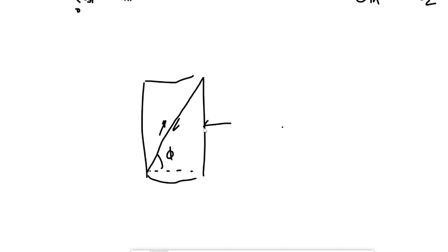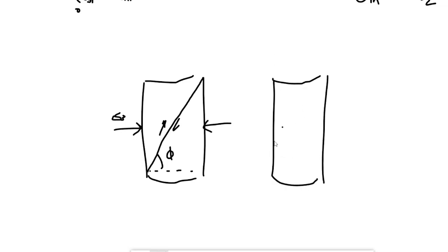And you start confining it, and this should become pretty intuitive. Look at this picture, where we have a pretty steep phi. This is sigma 3 here. Then I'll illustrate it the same way, drawing a similar cylinder here, where phi is really shallow. Shears are acting along it like this, and then you have the confining stresses. Now all of a sudden, they're acting much more horizontally. They're not opposing those shears nearly as much. They're basically just acting along the same direction as them. Versus in this case, they're really pushing that plane together and giving it more friction.